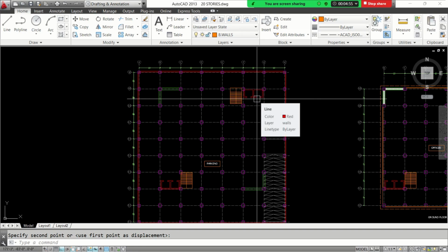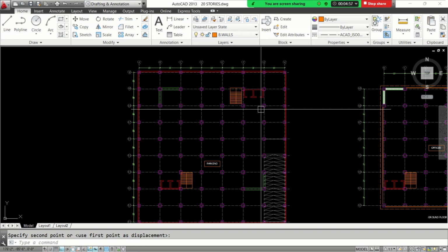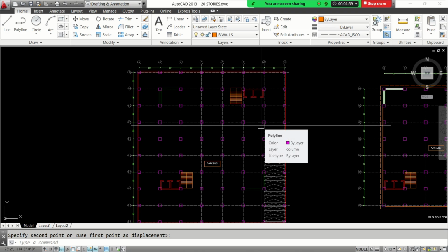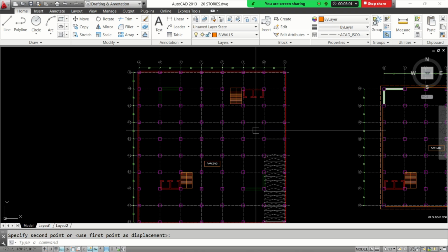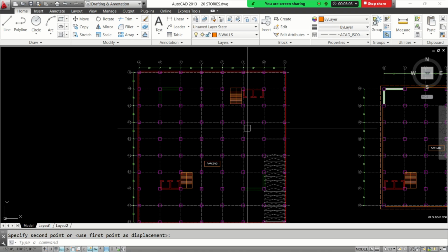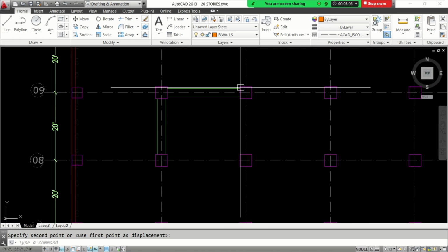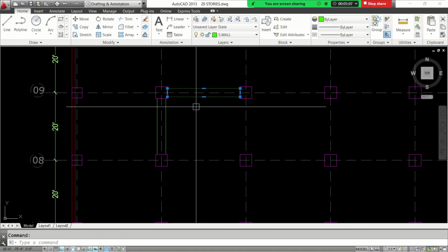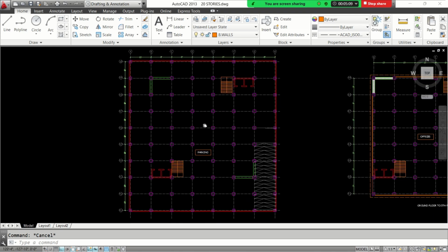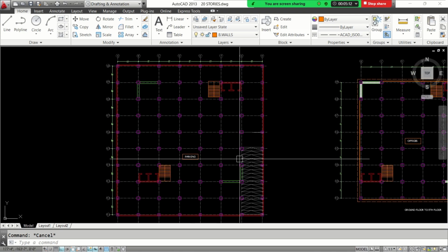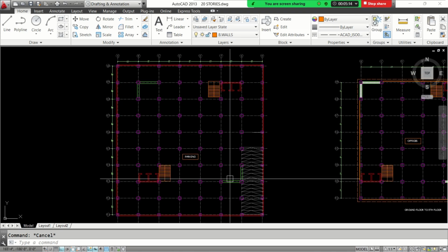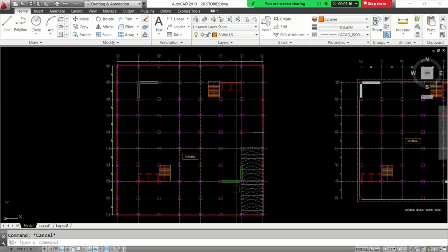But when you are designing your structure as a dual system, then you must propose shear walls, and you must locate those shear walls, and you send back that AutoCAD file or Revit file to the architect, so that he adjusts the architecture drawings according to these shear walls.